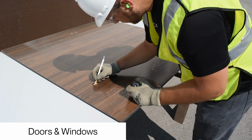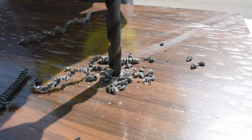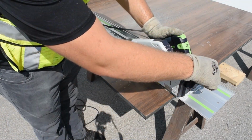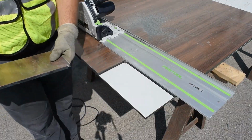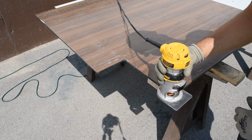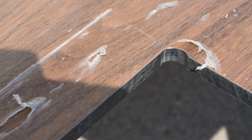When cutting for doors and windows, it is important to radius any corners. To make a radius corner, drill a minimum 5/8 inch hole in the desired corner location. Then proceed by making tangent cuts using the track saw. Use a hand router to chamfer the cut edges, and upon completion, you'll be left with a nice radiused corner.